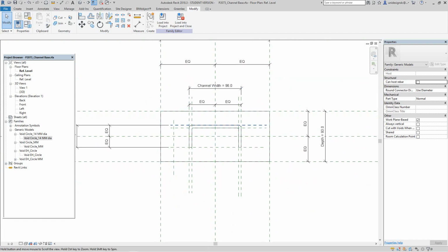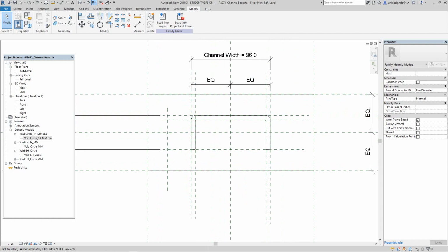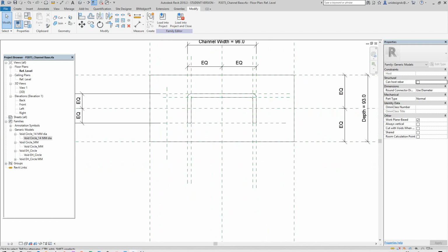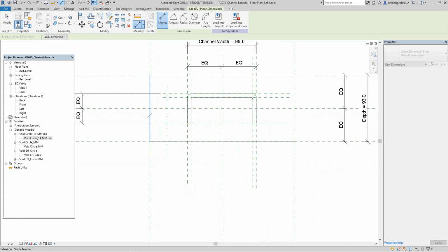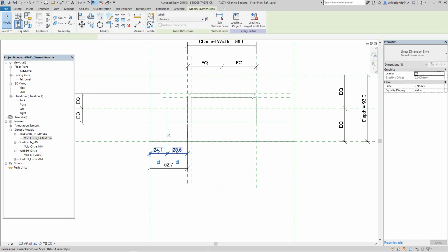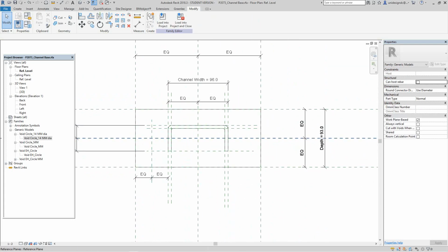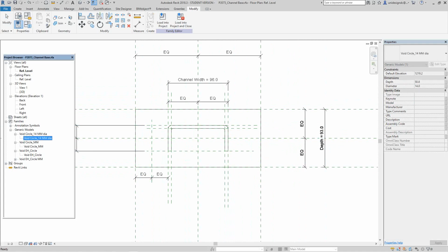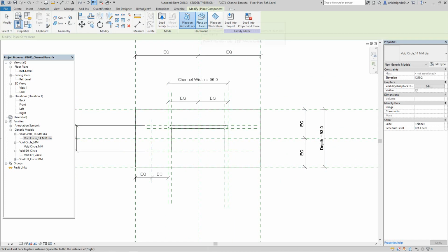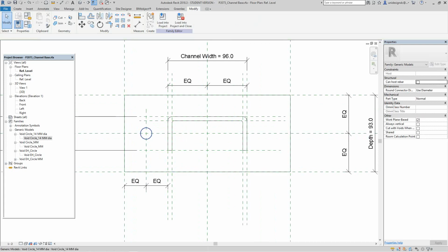So I'm going to just go and make this guy here. Just going to center this one from this point here. Let's go here to here. So if I can center that anyway, okay. So I don't need a parameter there. And then I want to center it this way, which is good right there. So that's the center point. So let's take your 14 millimeter hole and drag and drop it right there on the face. Bam. And then we could just mirror this over.